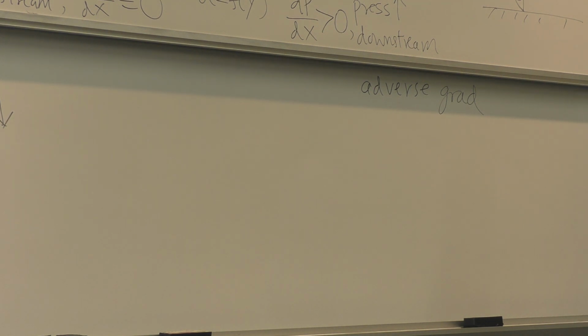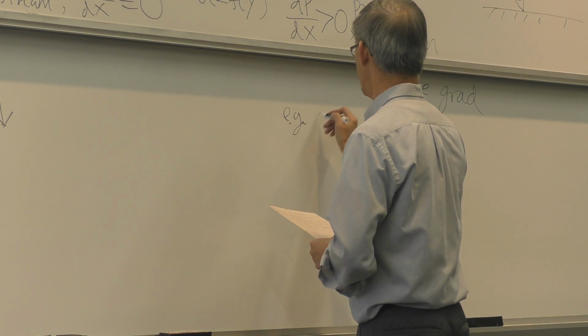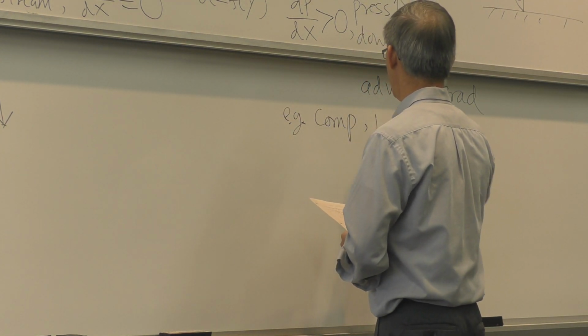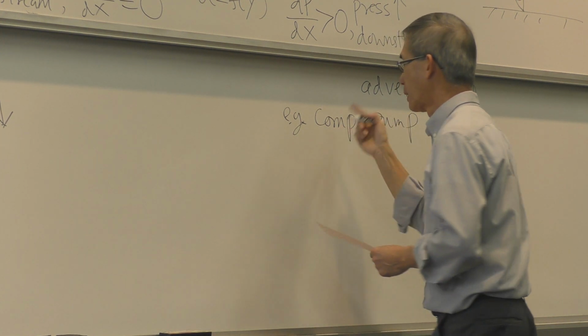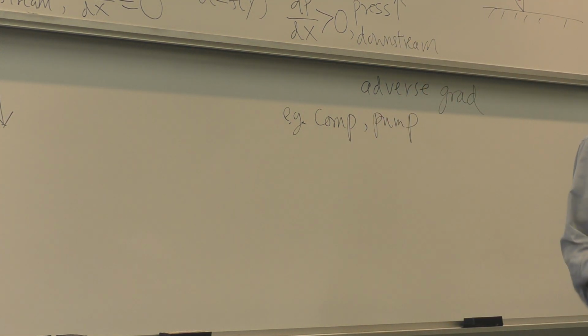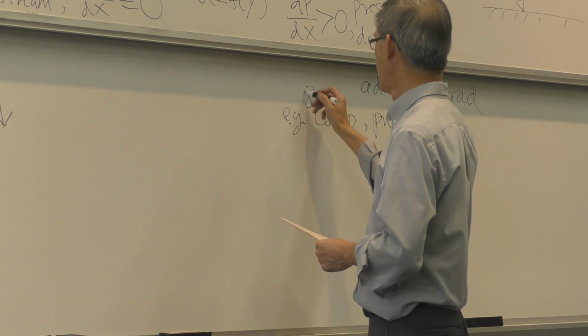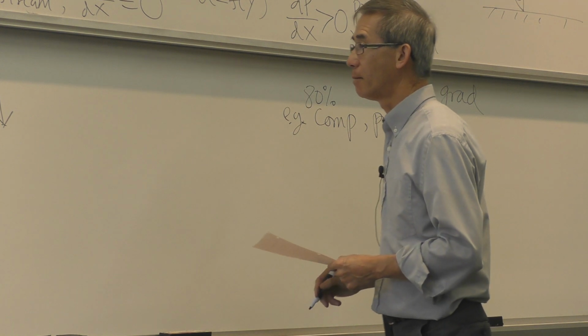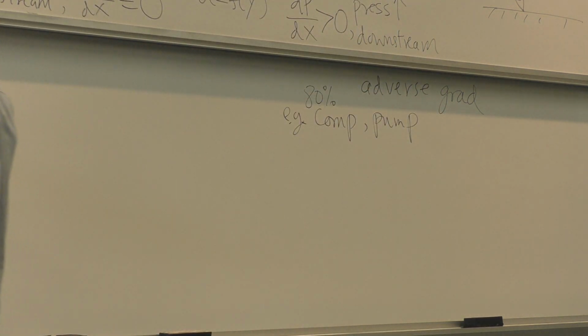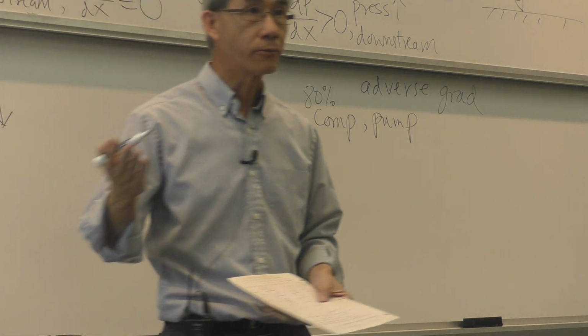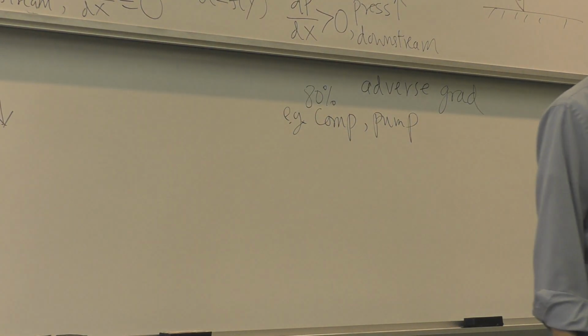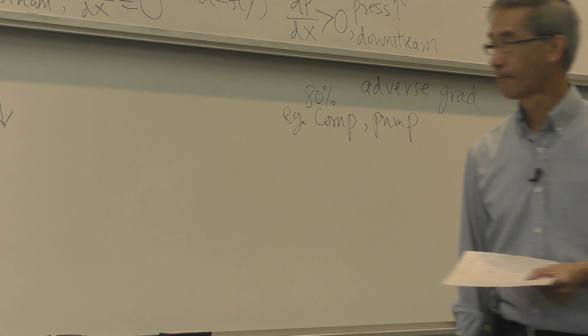What's the counterpart of the turbine? Compressor. Or pump. That's why compressor efficiency is in the upper 70%, or at most 80%. And so it's pump, but for a turbine, you can reach in excess of 90% because of all this potential for full separation. Okay.